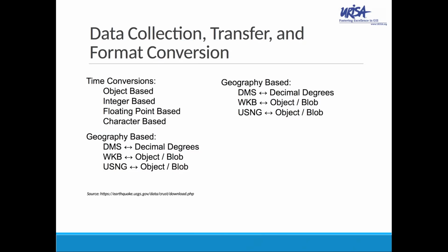If you haven't used it yet, there is a format for GeoPackage called SpatiaLite, and it is an ISO standard. It's also a US military standard. It's also an OGC standard. And Esri supports it in ArcMap and in ArcPro. You should know how to bring data into databases when they're encoded as WKT or WKB, or bring them back out again.